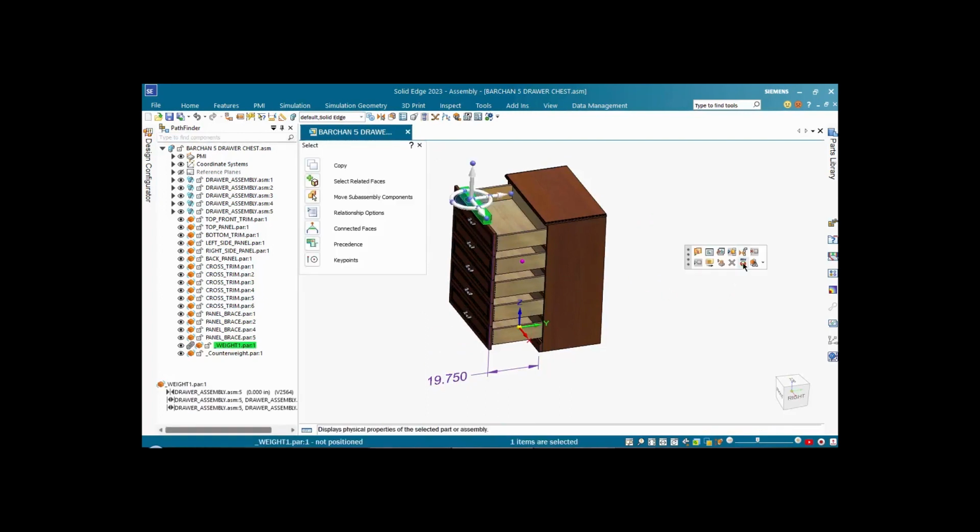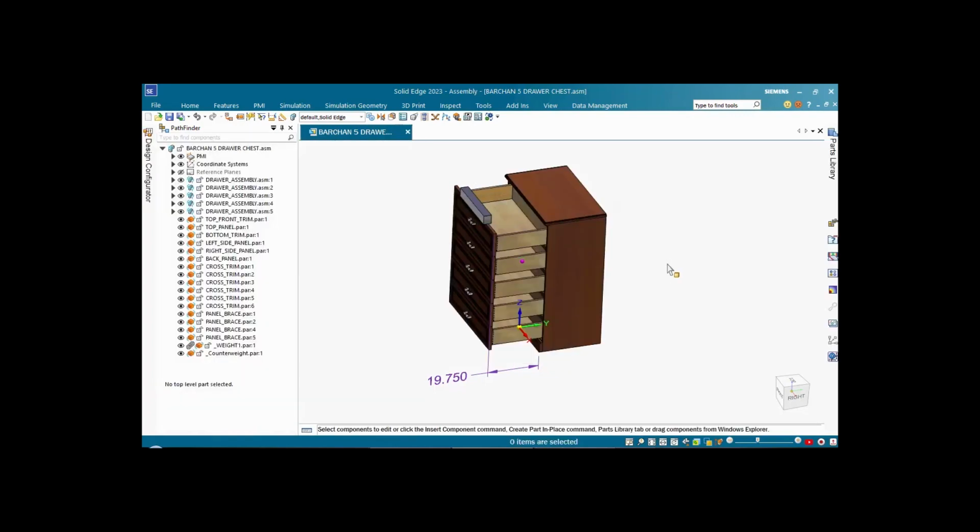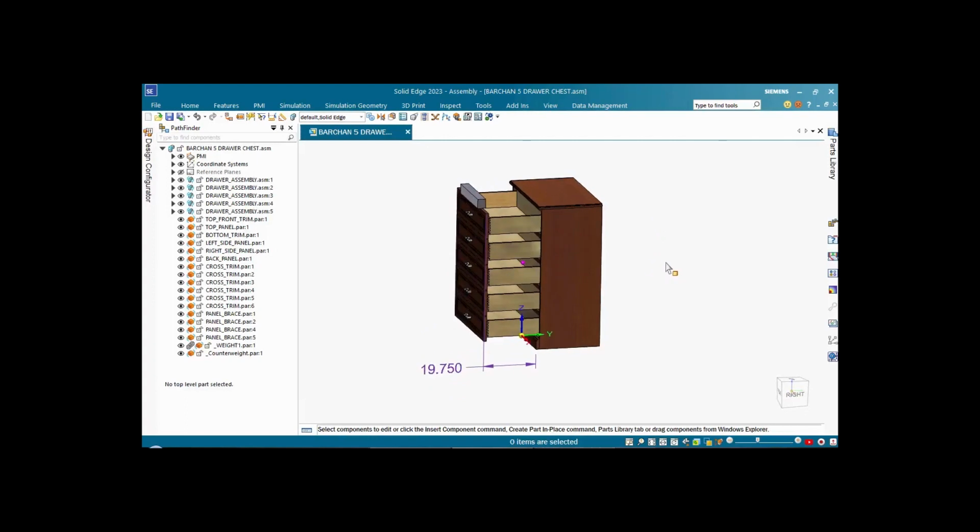So let's take a look at the value. We're talking about 71 pounds of mass that is required for the unit to start tipping over, actually over 71. This is the first method that we can use to figure out approximately the load at which the unit will start tipping over. I will present a different method using motion analysis.